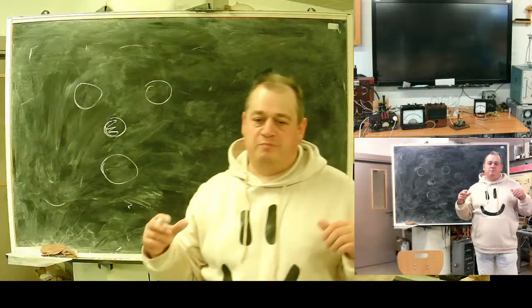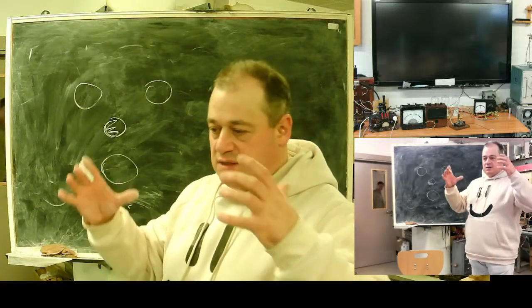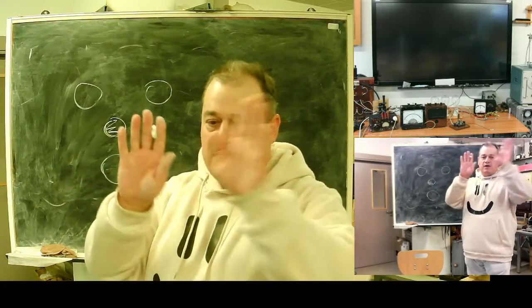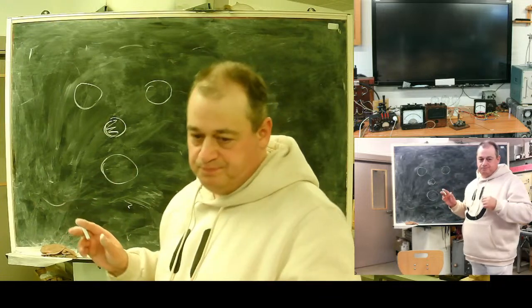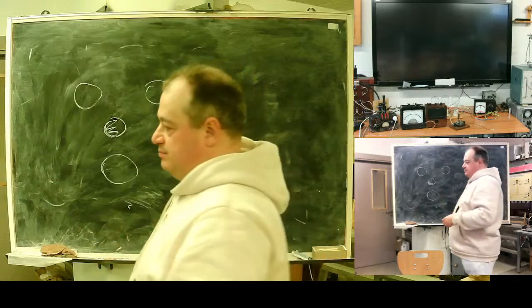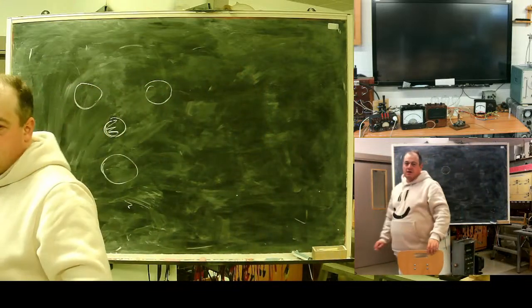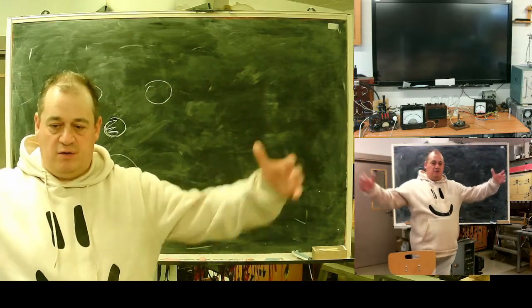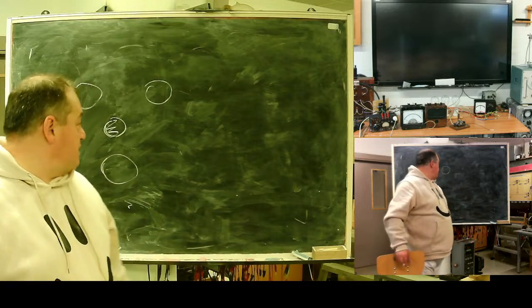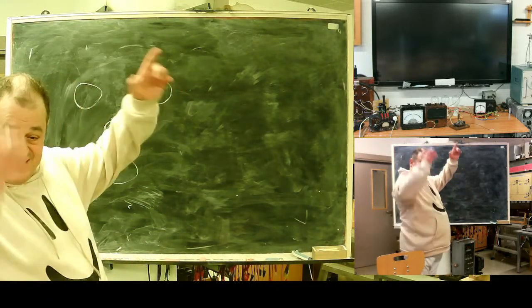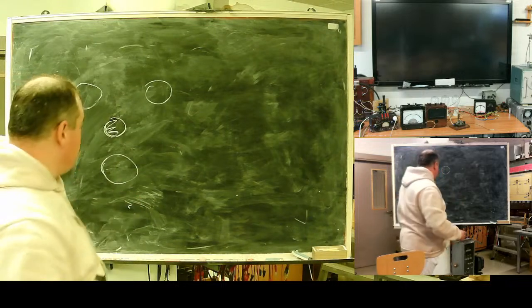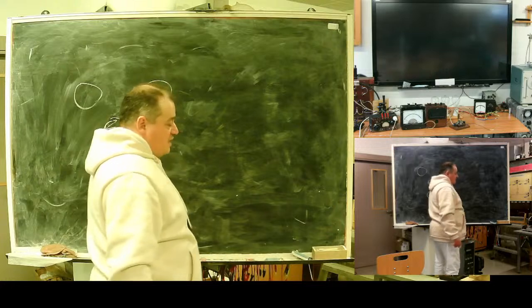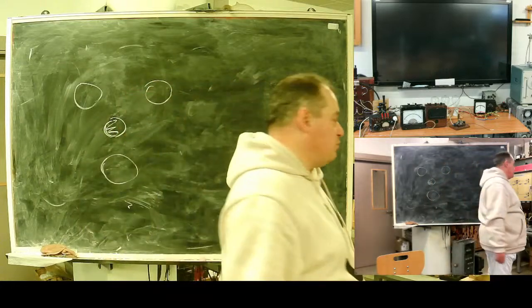Delta, not a linear arrangement of poles, but delta with the central leg. It may appear as a large barrel. Inside, it's a system with a central leg. Also the same thing. This leg creates a path for zero sequence.